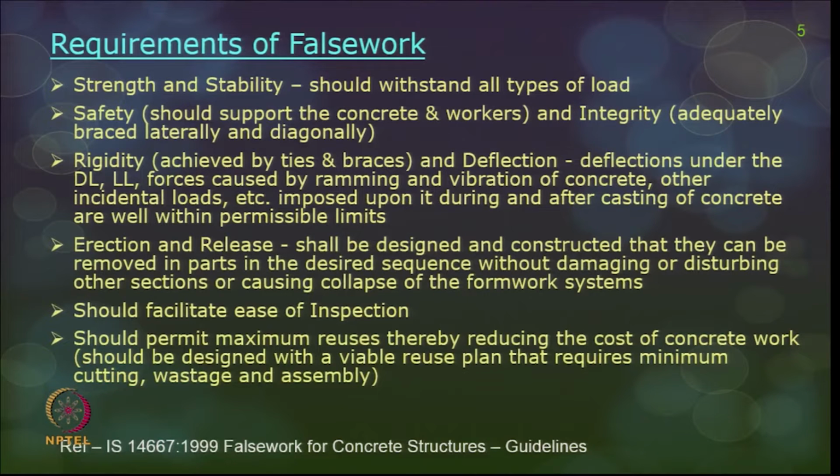So, first requirement: the formwork should have enough strength and stability, and should withstand all types of possible loads that come onto the formwork. It should be very safe, it should support the concrete weight and the workers' weight, and it should have a lot of integrity with the structure, so that whatever lateral or vertical forces come in, it remains firm and stable. It should be rigid, which is achieved by a lot of braces and ties, and the deflection should be within permissible limits.